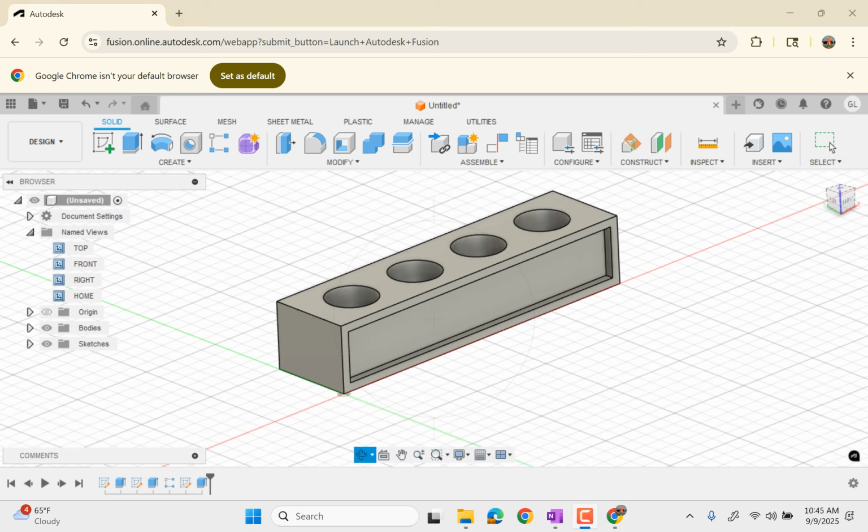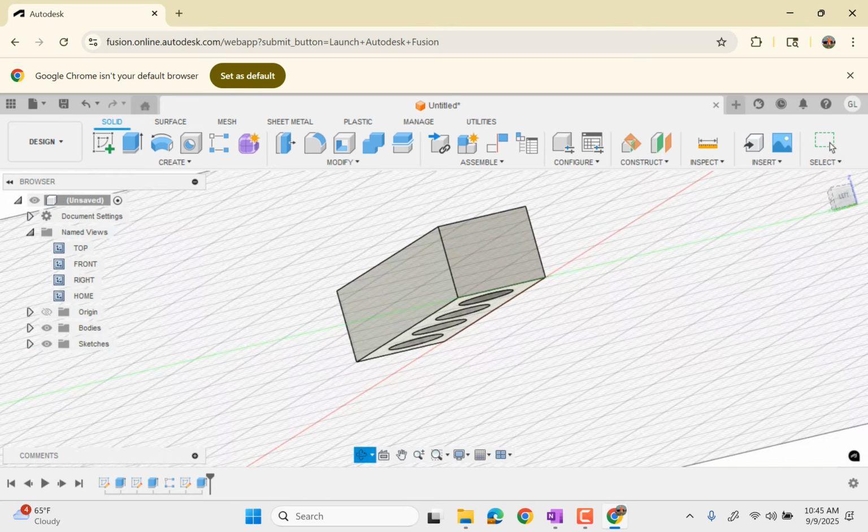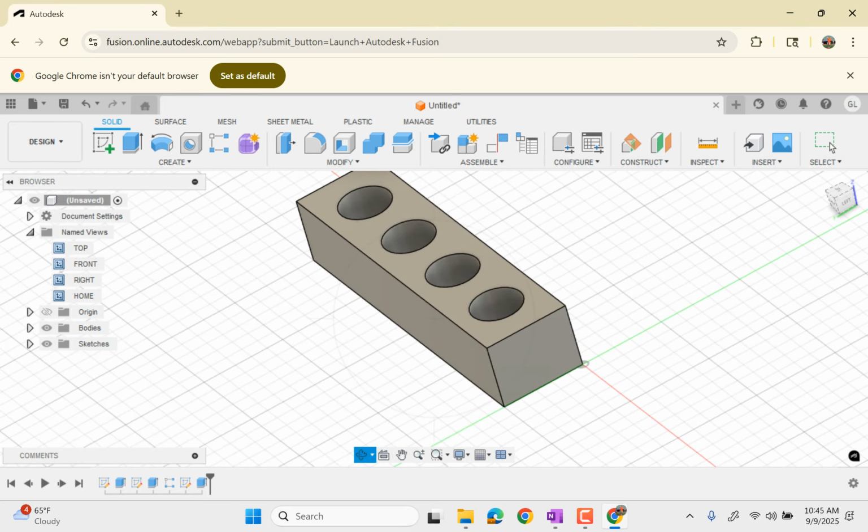Okay, so now I'm going to define a plane so that I can just mirror this feature to make it go on the other side. If I could make a plane that's parallel to this side, but just offset half of the width, that would be the plane that I would want to mirror that feature around. Can you see that? Question? How deep did you extrude in? Again? Oh, 0.05. Yeah.